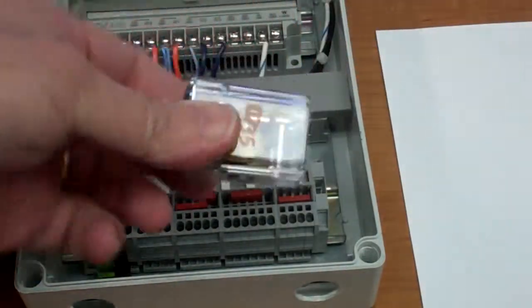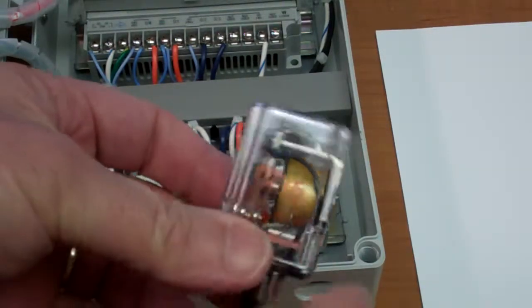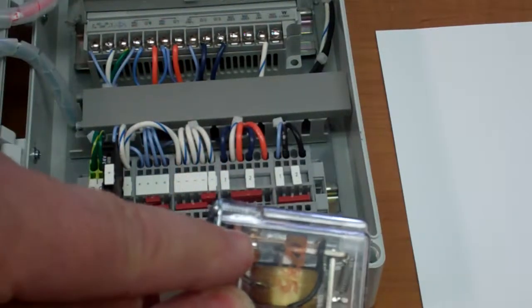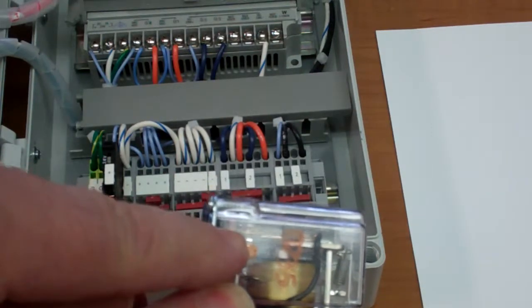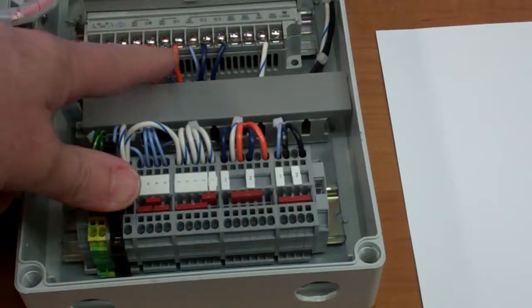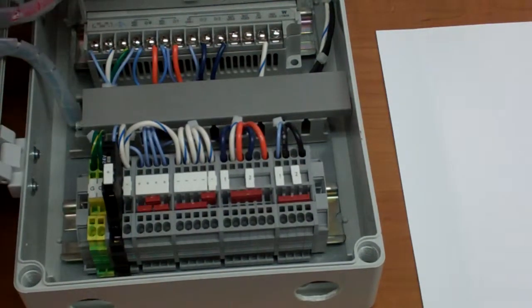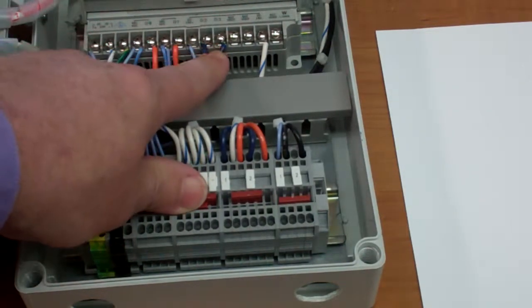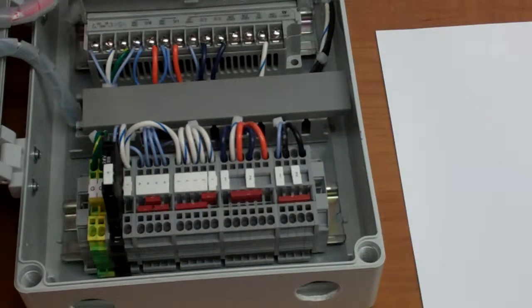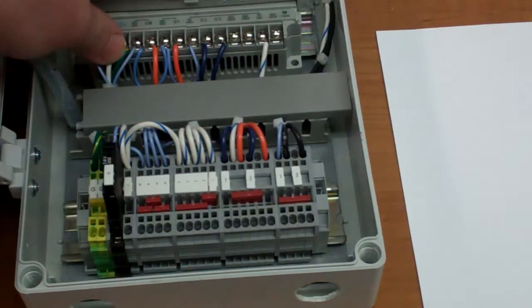This is a relay. It's a mechanical relay. You energize the coil. There are little pins in here, switches that can open and close. This is what's in the first two outputs over here. So solvent valves have a relay output in them. The air valves have a transistor output in them. When we first began selling these and saw people using 10-watt valves, we knew there was a problem coming.